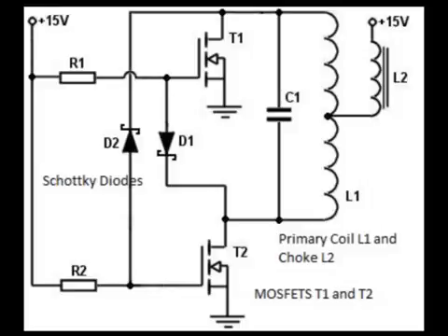Excessive heating occurs on the MOSFETs due to the internal resistance along the conducting path and power losses while the device switches between its on and off states. Because of this, appropriate heat sinks are required to evacuate heat.